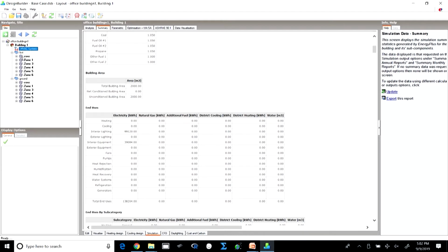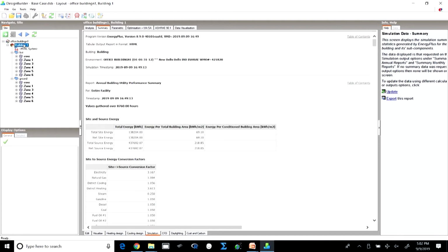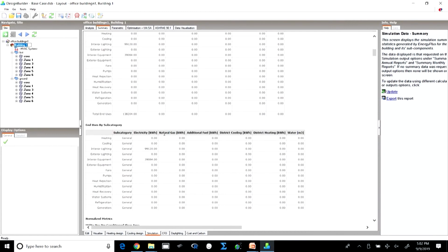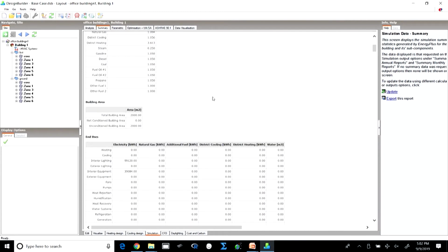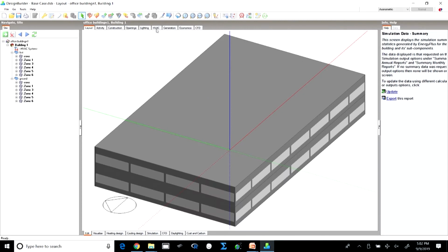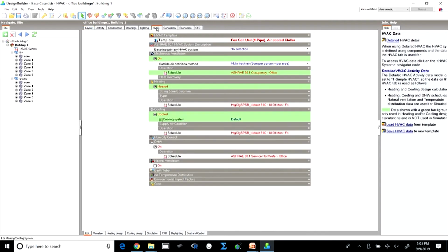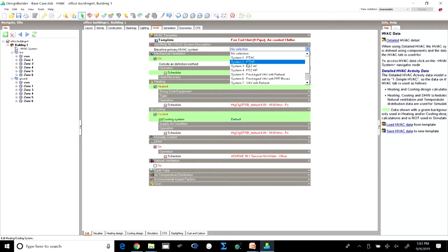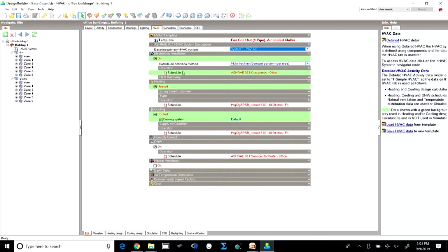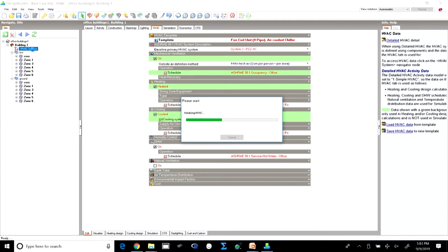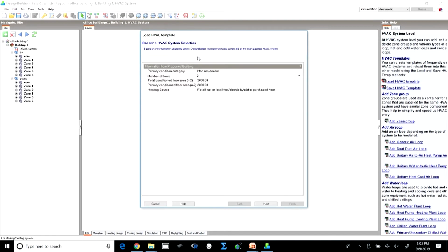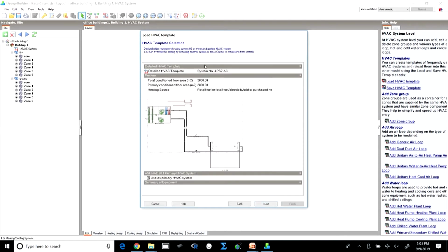while what we had intended was that we were creating the building to be fully air conditioned. So, we know very clearly that there is some problem. We can go back to editing the model and we can check the HVAC, because we must be getting the air conditioning load. Here the baseline primary system I select again as system 3, and we have the default cooling system, which is 3, and we are using it as primary system as well.